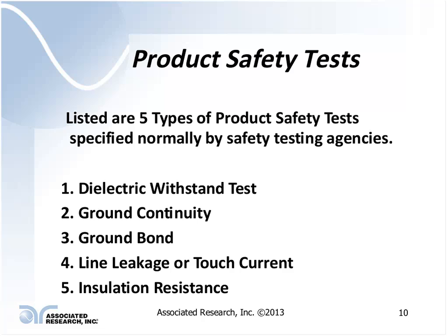When you talk about a Hipot test, a lot of times people say, well, it's a breakdown test. That's kind of a loose term. A breakdown test is typically a destructive test, one where you increase the voltage to the point where the insulation fails.